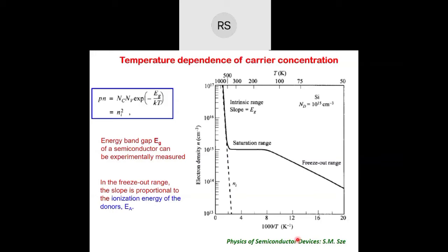Now what extra can we do? Just these 2 techniques, what extra information can I get about the semiconductor? If you have the option and facility to do temperature dependent measurements, let us see what it can do. I will just show you graphically. These 2 measurements you can do in the collinear four-probe method or van der Pauw geometry or precise Hall bar geometry. What you do is you measure the carrier concentration as a function of temperature.